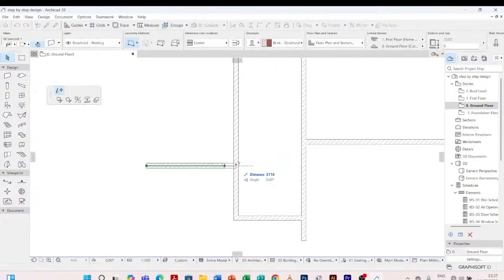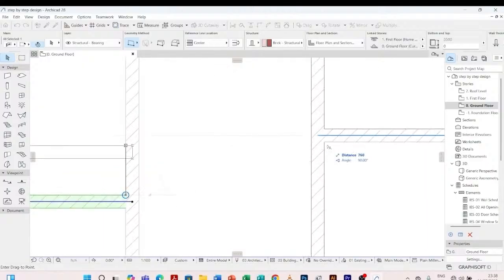So I want this wall, from this wall I want it to be at 1.2 meters. So I Ctrl D, that is moving a copy. No, that is, sorry, dragging it. Then when I'm to move it, I hold on shift to get the exact point.